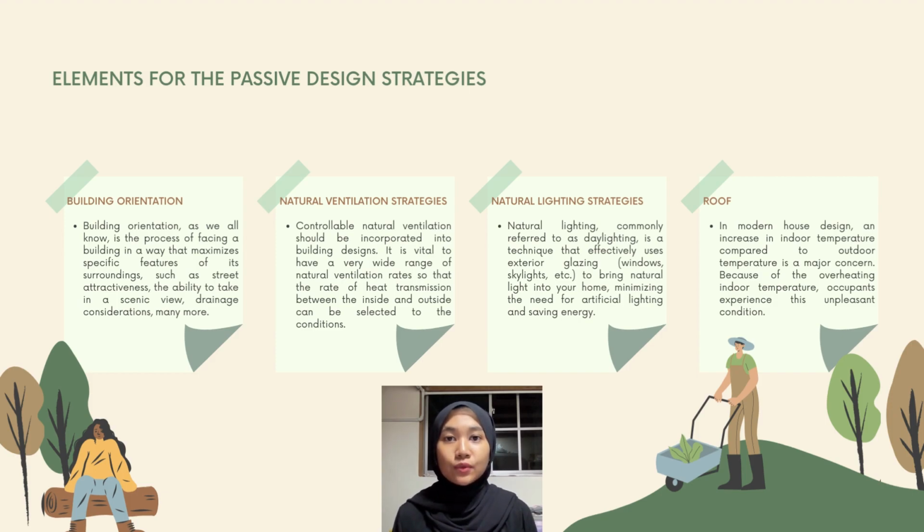Building orientation, as we all know, is the process of facing a building in a way that maximizes specific features of its surroundings, such as street attractiveness, the ability to take in a scenic view, drainage considerations, and many more. It all comes down to balancing the project's budget, program, site requirements, and microclimate to determine the best mix of active and passive solutions to use.